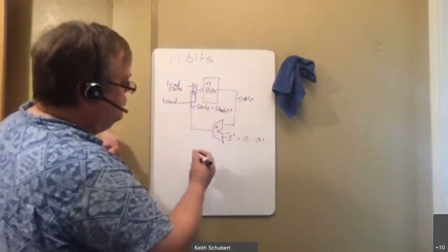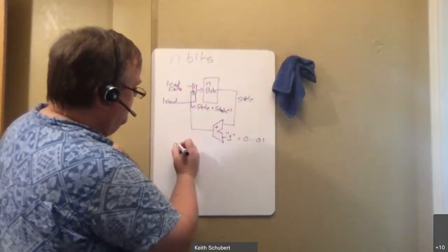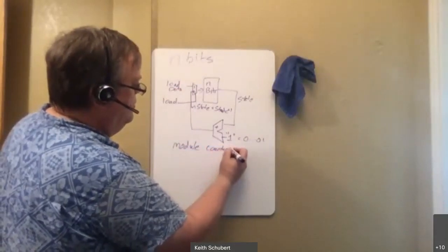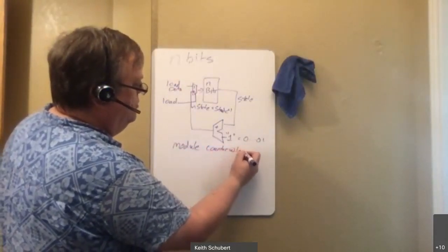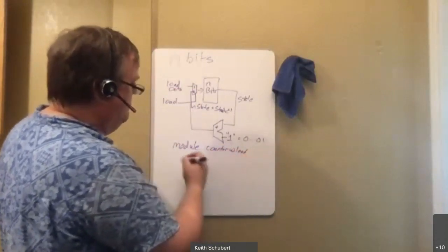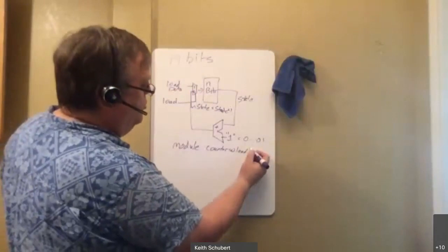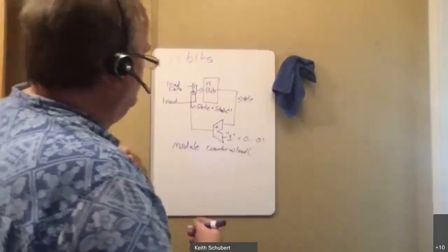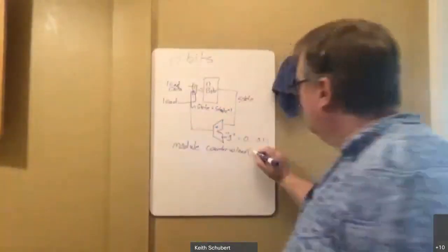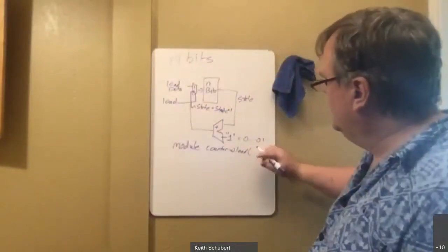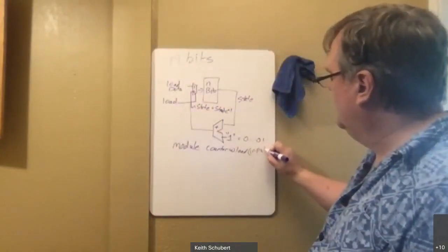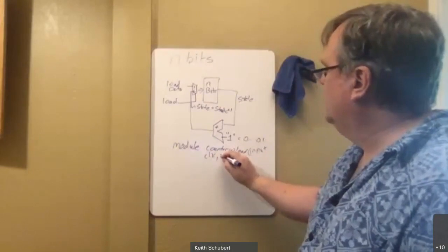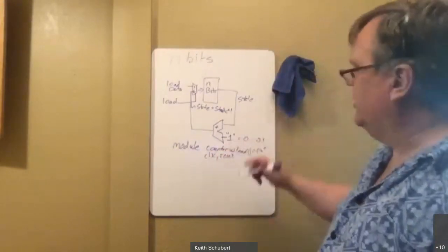It's very simple. In terms of making a module in Verilog for this, a counter with load. So I might want to be able to have a counter with load, and I'm going to need to have several pieces of things that are input. I haven't shown it here, but I would need an input, need clock, I need reset or clear, either one you want to call it.